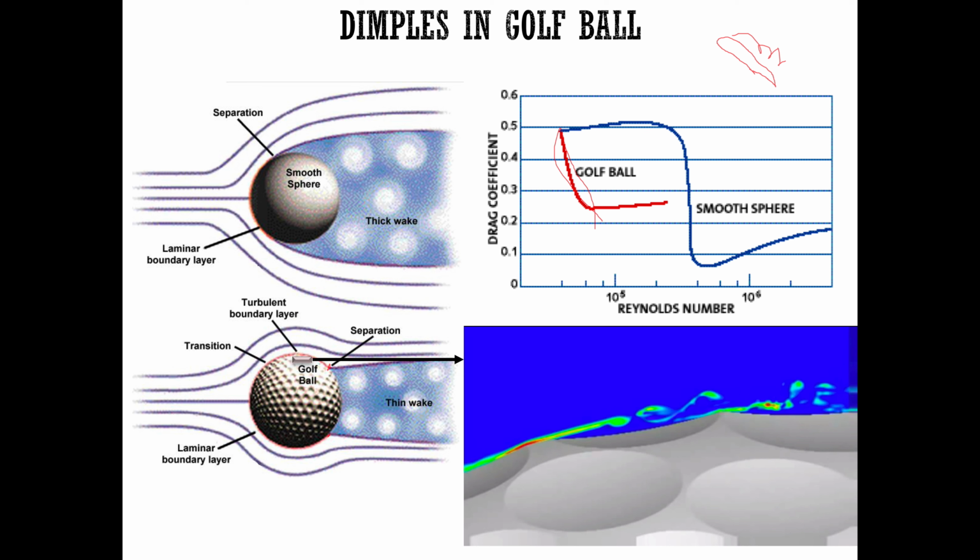And people have also tried doing that on a wing, just to see how dimples on a wing will affect it. In some cases, at some Reynolds numbers, it works and has benefits, but then again, as I mentioned, dimples on a wing and a golf ball work much differently because a wing is a streamlined object where skin friction dominates.